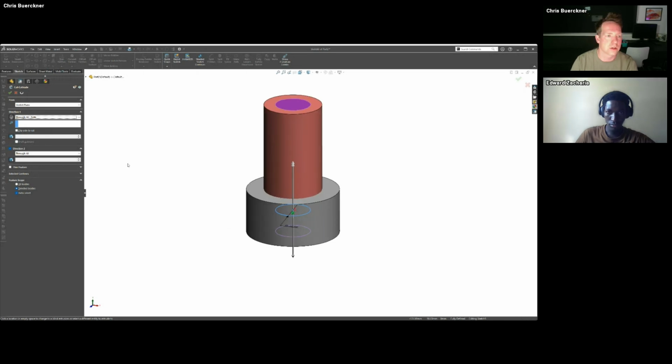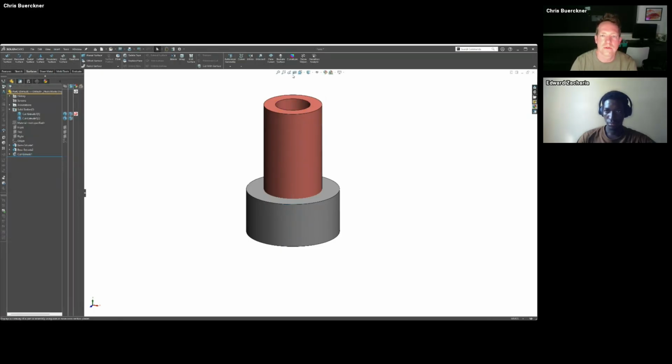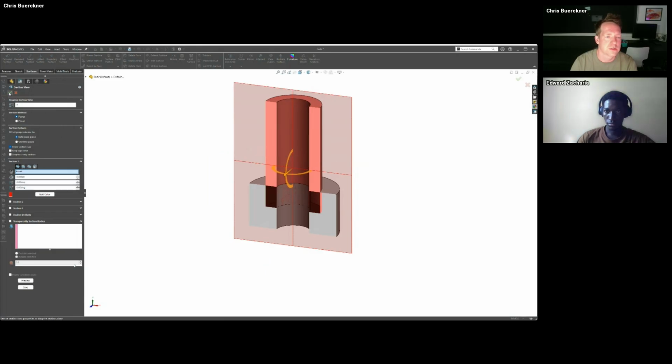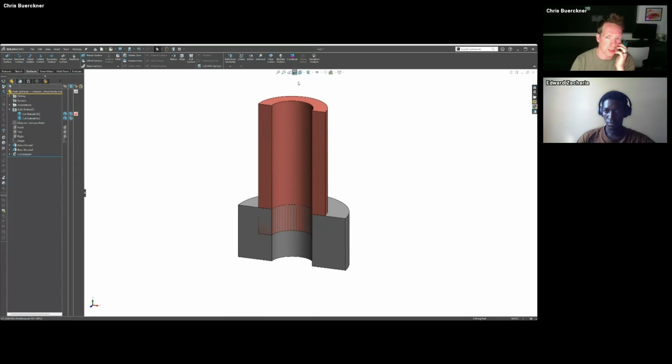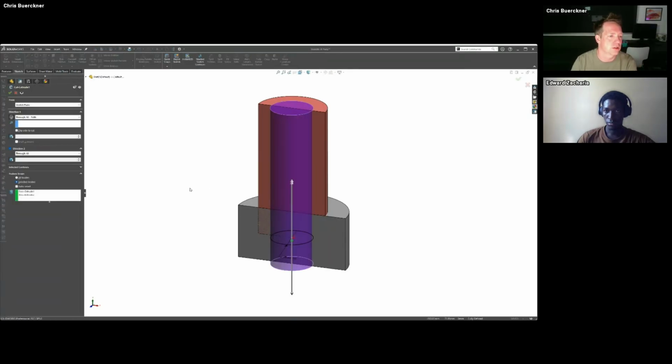And what I'm going to do is, if I was just to do the default thing and just press OK, you can see here in feature scope, it's got all selected bodies, but auto select. We do a section view. We can see it's gone through all the bodies here. But what the multi-body features allow you to do is edit that cut extrude.